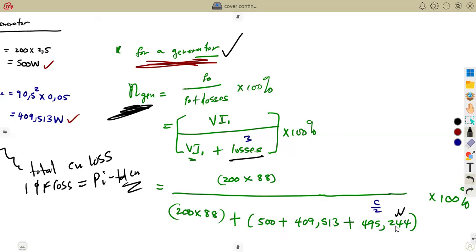It is shared equally for both machines. It is there on the motor. It is there on the generator. So do not confuse the last one, the iron, friction, and windage losses. So that is how questions might be given working with the regenerative method, which is our Hopkinson's back-to-back test.